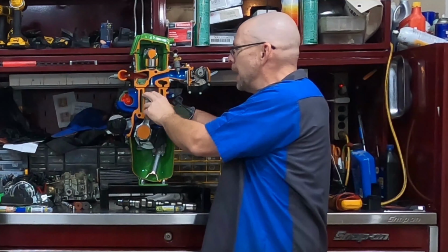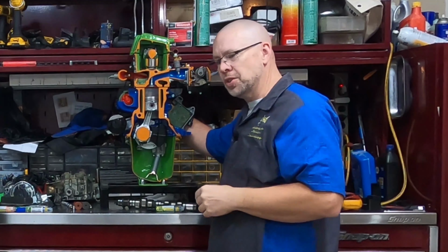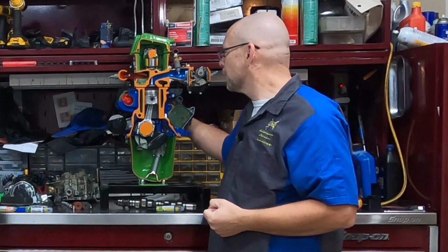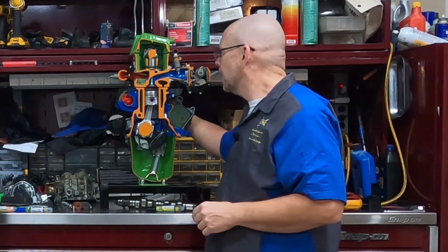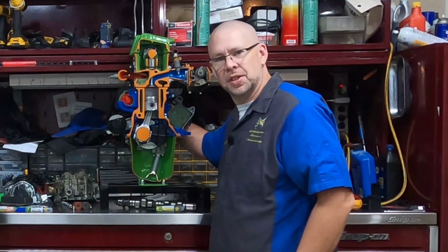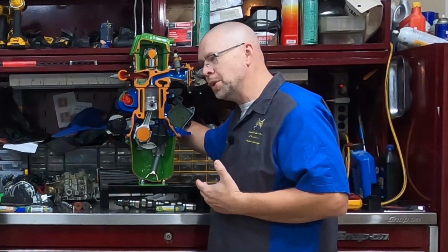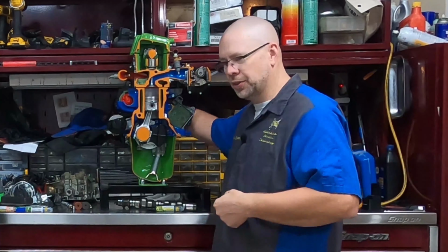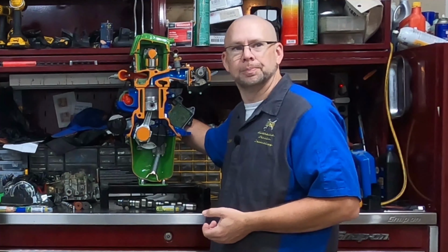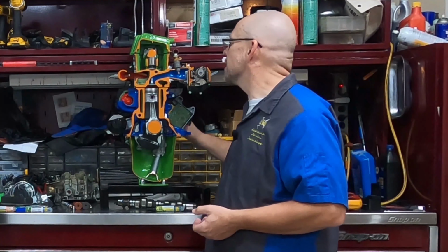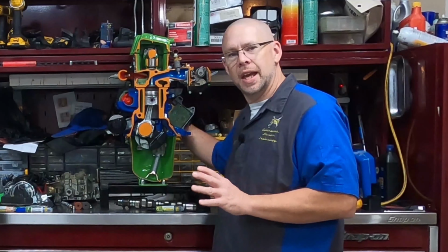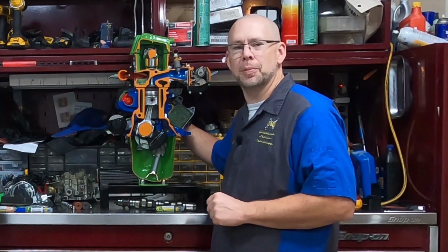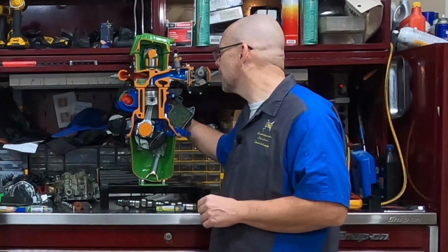This space is expanding in size rapidly, and so we're not really taking any more advantage of that energy. If we don't have our burn timed correctly, we end up just kind of chasing the piston down, and we don't transfer that power, that energy to the piston, through the crank, out to the wheels. It doesn't do us any good. It's a waste of fuel. So ideally, we always end between 10 and 20 degrees after top dead center. It varies a little bit depending on engine build and design.